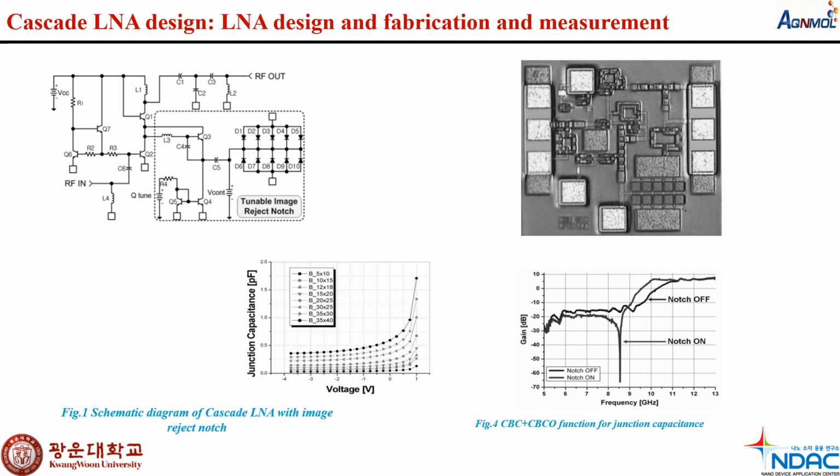So this slide will talk about the Ku band LNA design and fabrication and the measurement. The LNA design prioritizes low noise and power consumption. Here it is broken down. First of all, the transistors Q1 and Q2. Two emitter fingers to minimize the base resistance, with a specified bias current of 6 mA for low noise and power efficiency. Q2 acts as both a mixer and driver transistor.